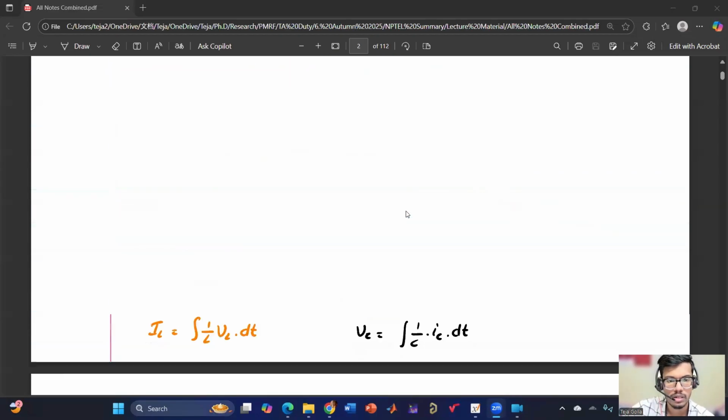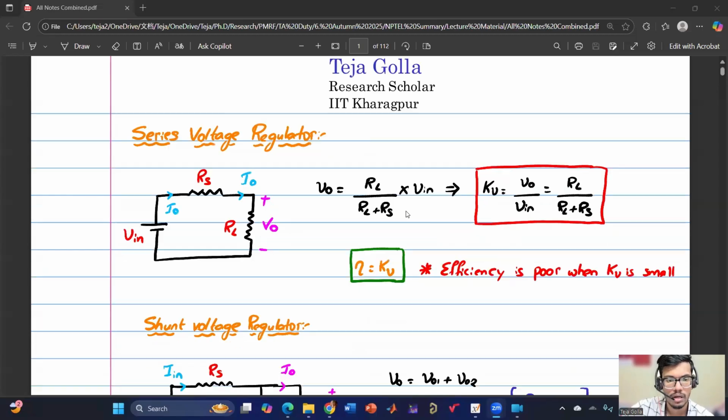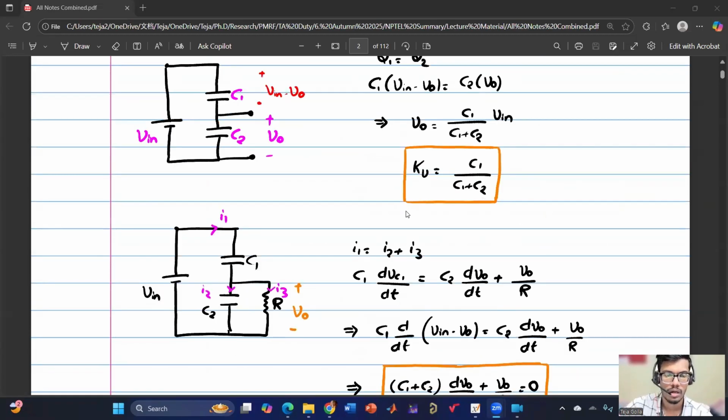In that, two circuits are given, a step down and a step up, and that operation is clear. But if we want to derive the expression for output voltage, like what we did in buck and boost examples, where we used inductor volt-second balance, is there anything like that? Yes, you can do capacitor charge balance.